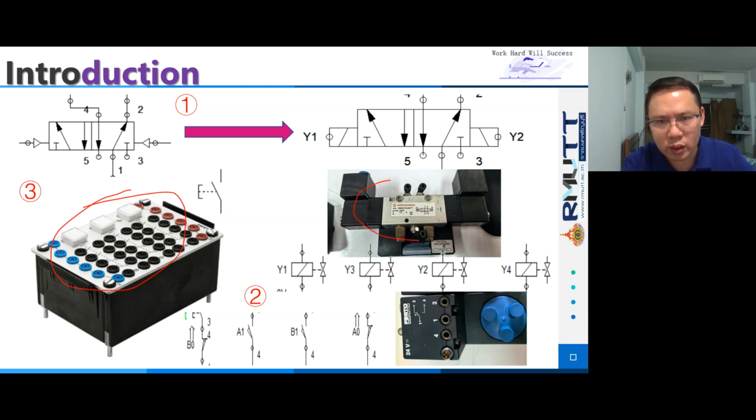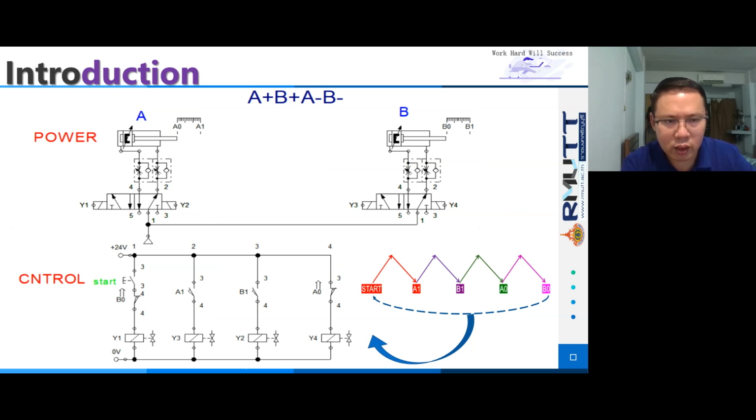We can use the limit switch, and in the diagram of the electric pneumatic system by the FluidSIM software, we can say when we press the start, this is working and connects the Y1. The Y1 is working and the A plus motion begins.